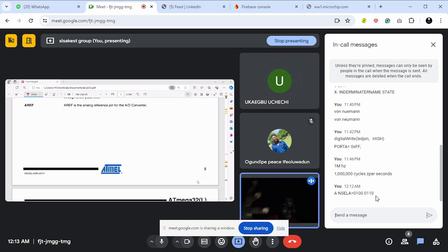You are now seeing that. So in runtime now, this one will make the first pin, this is pin 40, you understand? Make it a digital pin. Make the next pin an analog pin. Make the next pin an analog pin. Make the next one a digital pin. Maybe you finish your analog to digital conversion and you run out. You still want to do digital. Then you come back again.